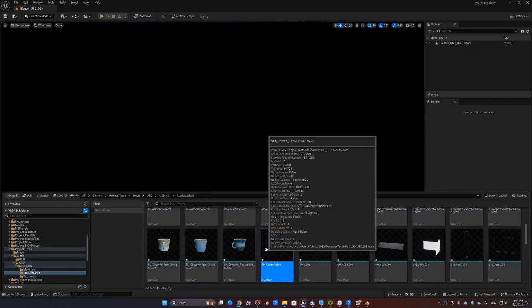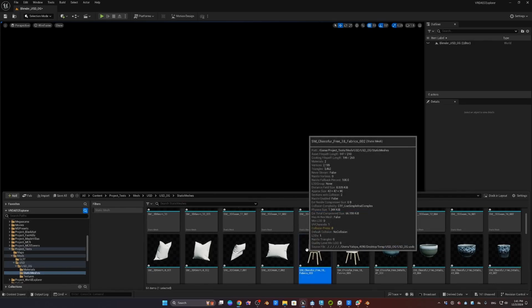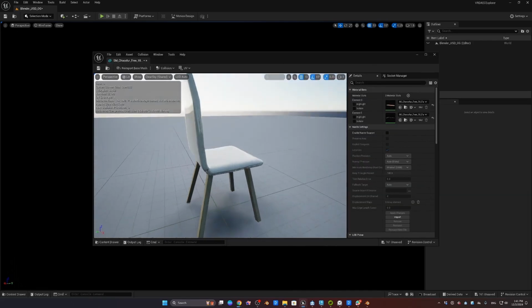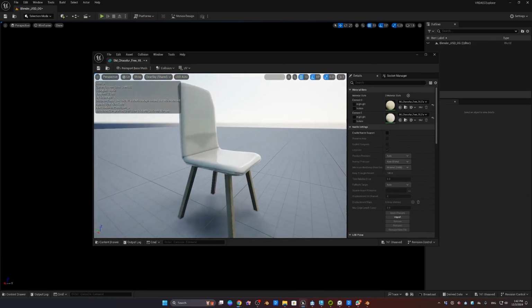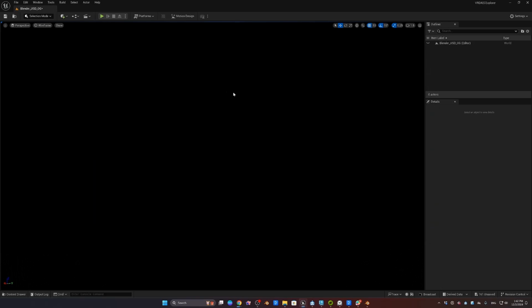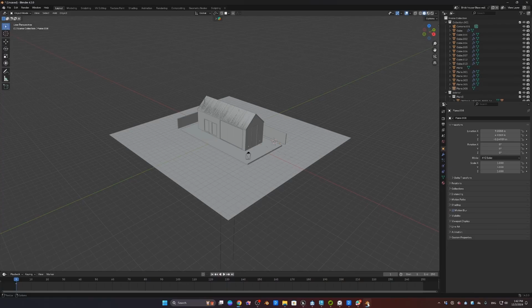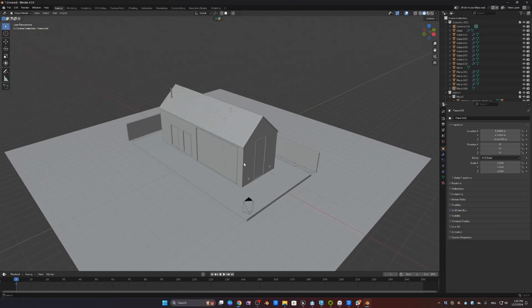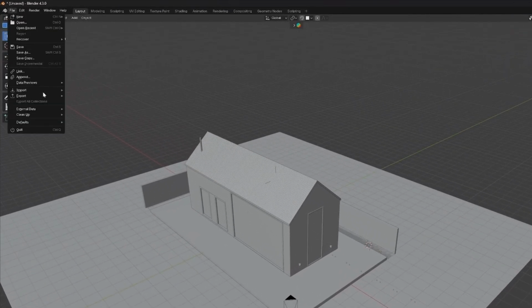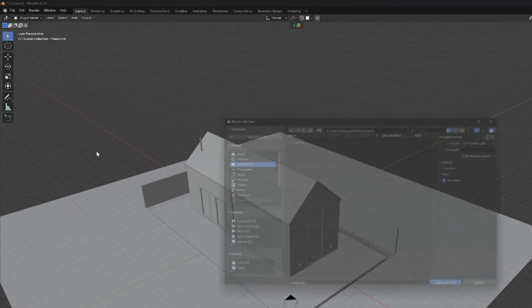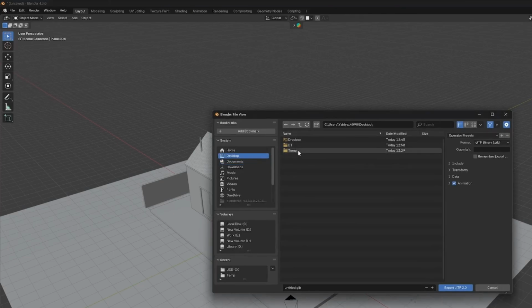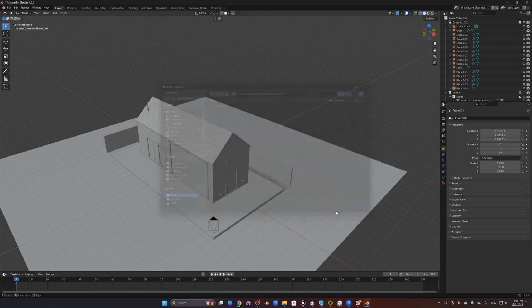So when it comes to exporting full scenes, if you want to maintain the best quality possible for one simple asset, you can do that, or a couple of assets. But when it comes to a whole scene, one trick I use is simply using GLTF. So from File, go to Export, select GLTF, and let's go to Desktop where I have my file here, and I will simply put GLTF. I will open it, and I will name this test, and I will click on Export.